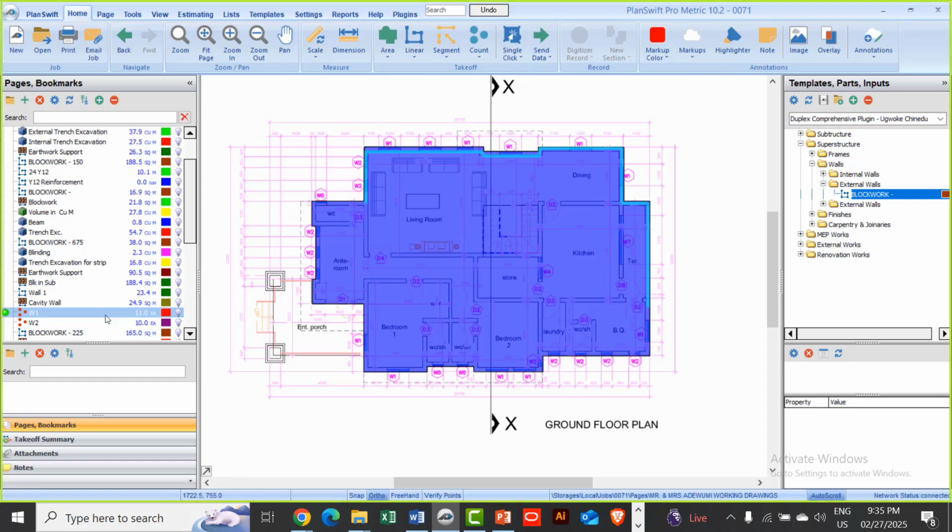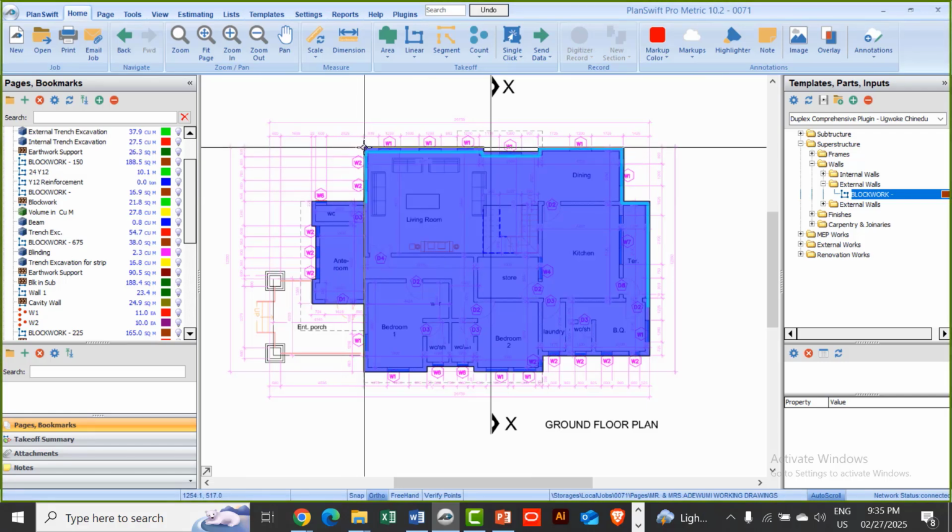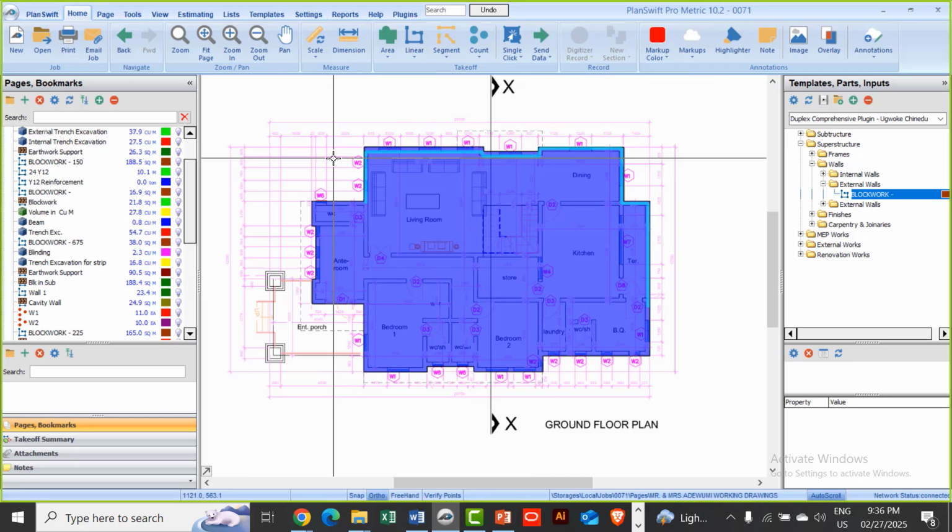Now you do your oversight concrete. In some cases, for some kinds of buildings, you want to do your iron work or your reinforcement, you're going to be using wire mesh. So most people use wire mesh. Good, BRC mesh. Your BRC mesh is measured in square meter. I've mentioned the first time that if you say concrete work, it means your concrete is involved, your formwork is involved, and then your iron work or reinforcement is involved. Your tying and fixing of reinforcement is involved.